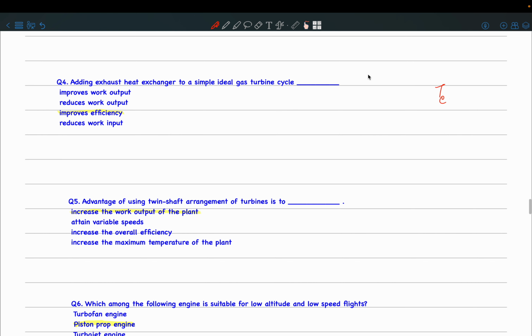But I also said that T04 is the inlet stagnation temperature of the turbine. So from T04 to TE, that change determines your exhaust velocity. So now if you add a heat exchanger at the exhaust and you reduce TE further, then your UE is going to increase, isn't it?